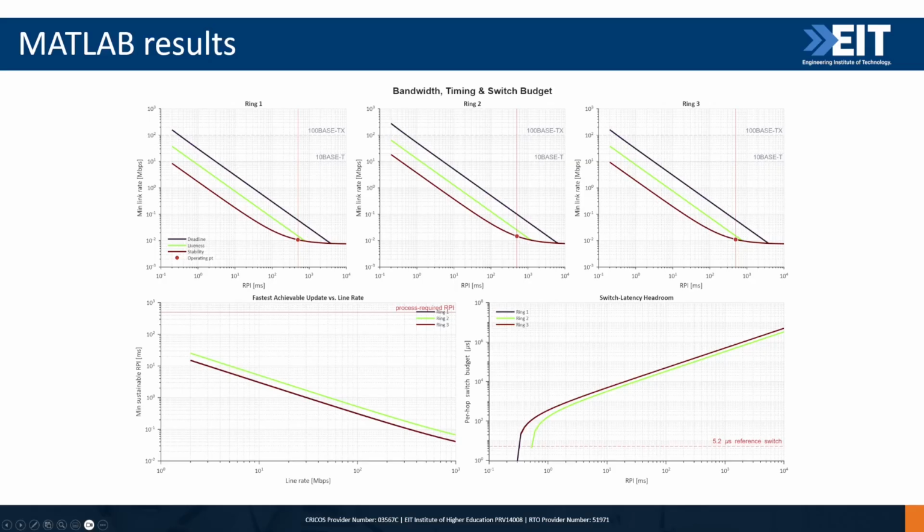From these results, I'm postulating that as the expansion of the nodes increases, requiring more switching due to hops, the DLR ring recovery time becomes more of the driving constraint, which would also drive the switch constraint as shown in the bottom right.